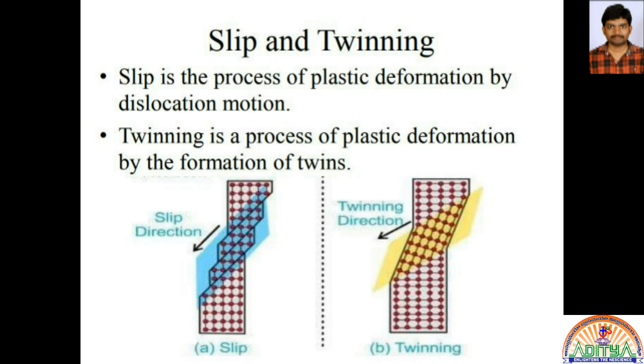Slip directions are the directions along which dislocations move. The important thing is the critical resolved shear stress, the minimum stress required for slip to occur.